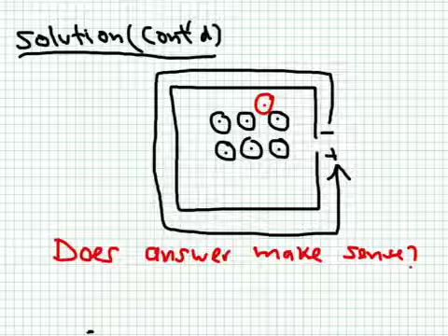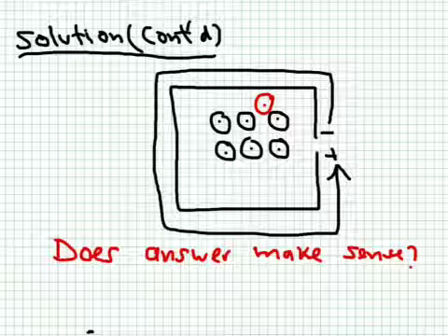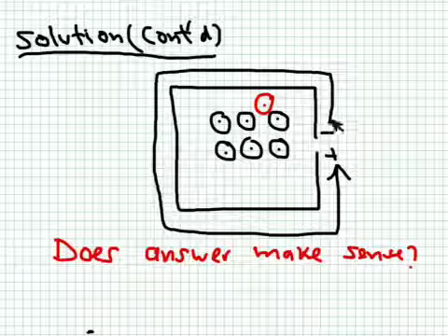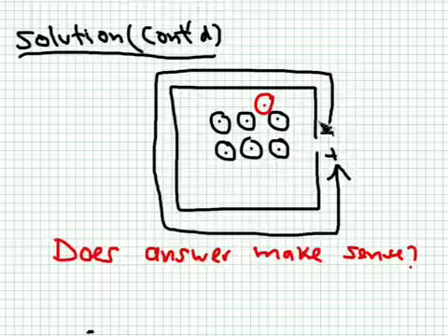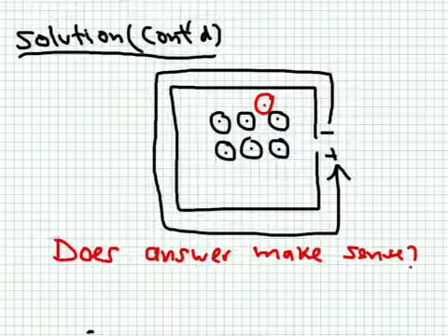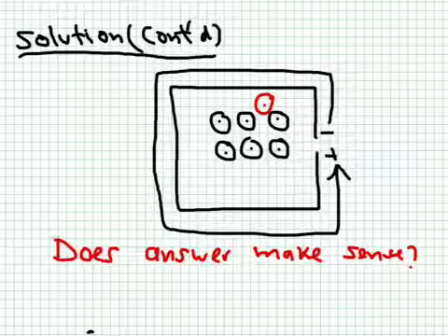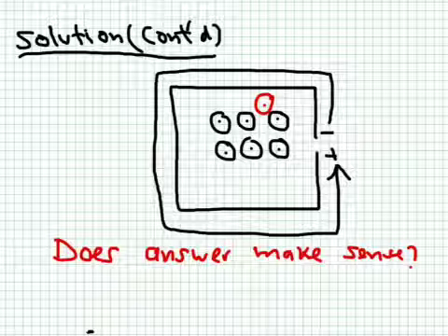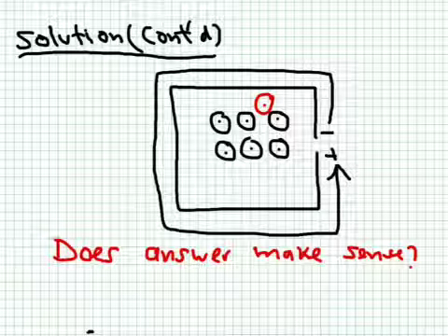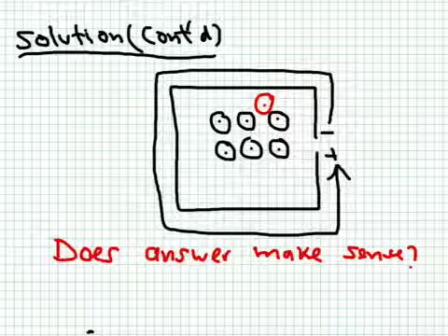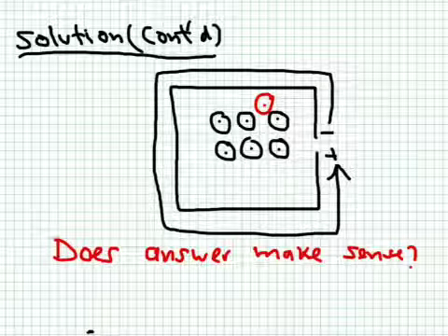So here our answer will be that yes, the electric current created has a sine profile. Sine profile means it's increasing with time between these two terminals. So if you close the circuit, there will be a current trying to stop the decrease happening in the flux, because the flux starts as a minus sign, it's decreasing with time. And you can follow that exactly at every time step. The current will always be such that it's creating a flux that's trying to oppose the change happening in the flux going through the circuit.